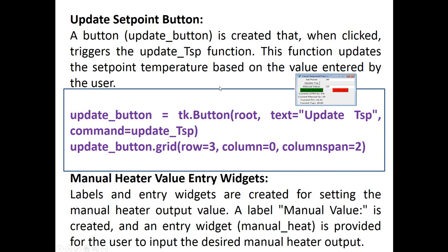Then you have to manually, suppose you want to test, give a step input manually to it and see how the profile is going. You have to take it to the manual mode here, or manual override it is called. One more time and another time, if you press on this, whichever comes green, that is what it is working on. This is a manual mode. Otherwise you can click on this, it will become green, then it will go to auto mode.